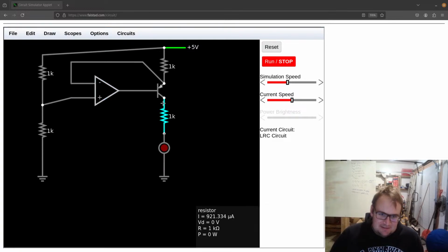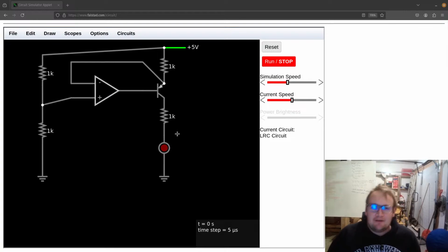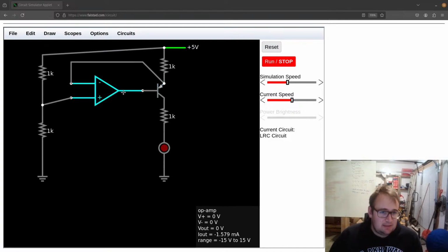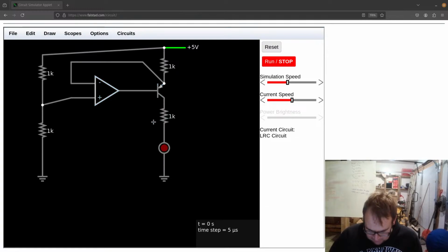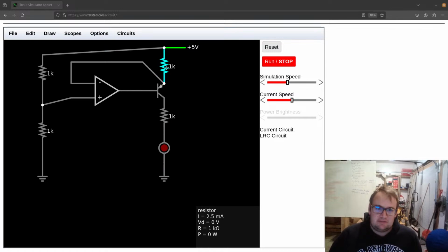But anyways, so I set this as the load, which, any load, it doesn't really matter. I always set it, but that's not really what we're looking at, right? Now, what it does is that it says that we can calculate the current, the I load, the current of the load right here, using the formula VCC minus VN divided by R, which this is R here.